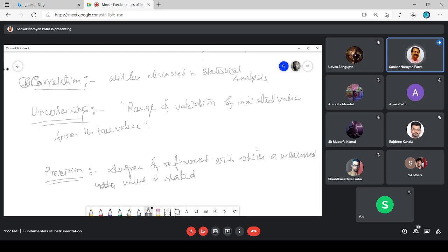Okay. Now you have an instrument which measures the boiling point of water on the first day as 100 degrees centigrade. The second day it measures 103 degrees centigrade. The day after that you measure again, and it's showing 99.8. The next day it is showing 99.99. In this way, you can say the instrument has better precision, and is highly accurate.